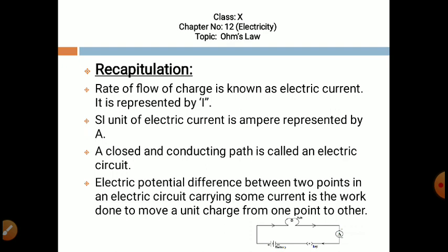And if the circuit is open, then you all know there are minimum 5 points. Any one statement may be true from these 5. That is, the indicator, which is the bulb, may be fused, there may be a loose connection, there may be a cracked wire, the switch may remain open, and the fifth one is the battery or the cell, the potential providing to the circuit, the battery is dead. The circuit will be known as an open circuit, and the bulb will not glow, as you can see in the figure.